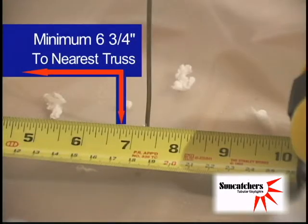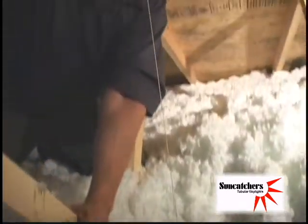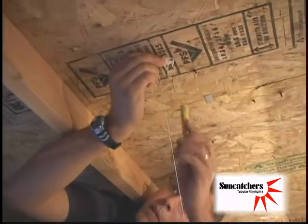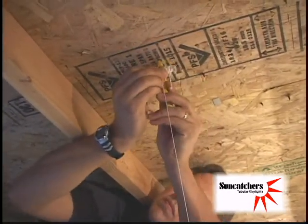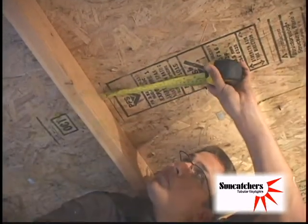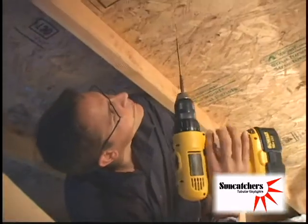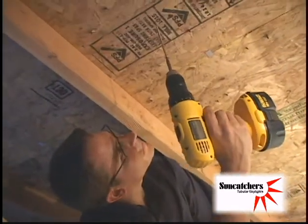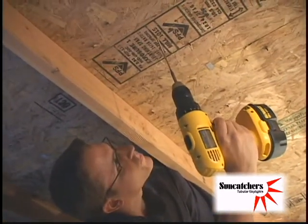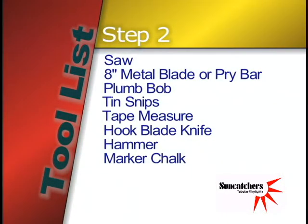If your marker is too close to the truss, you will need to make a new hole down through the drywall. Drop a plumb bob from the roof to the wire and mark the position on the roof. Measure from that mark to ensure you still have at least 6 3/4 inches clearance to your nearest truss. At the mark, drive a screw or nail through the roof sheathing so you can later locate this on the roof. Step 2. Tools list.